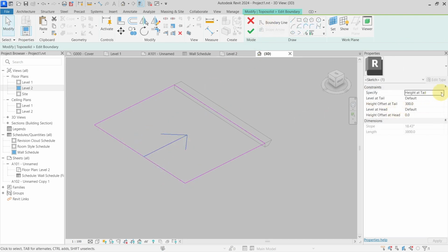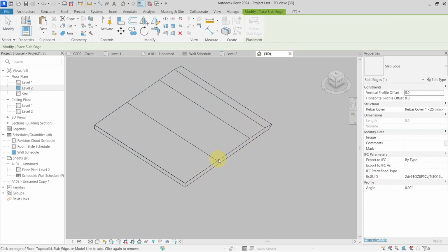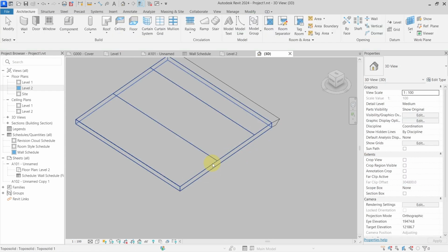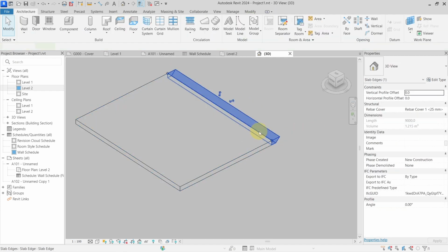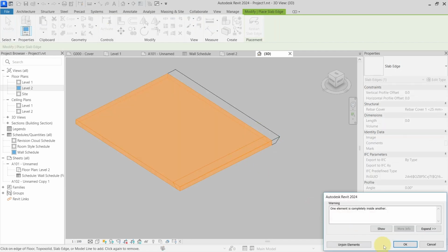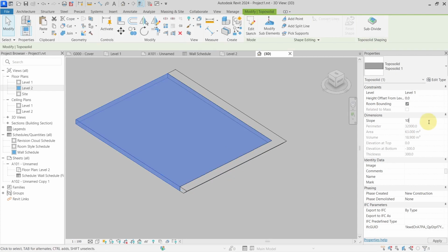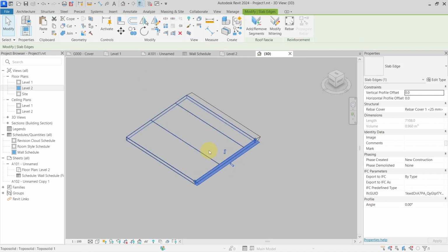with the slope, and let's go with the slope 0, let's place it 10 degrees. Okay, and I try to place my slab edge on this edge, on the sloped edge, you can see that I cannot actually do this. There is one trick, the same as with the floors, and that is that if I go and undo the slope, then create my slab edge, and now if I redo the slope, now you can see that I was able to create the slab edge on this edge.